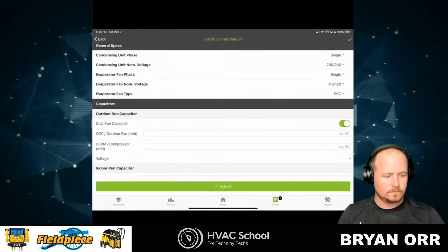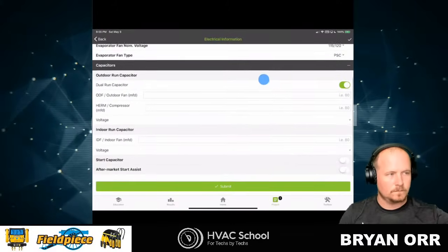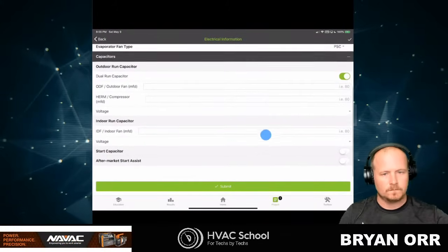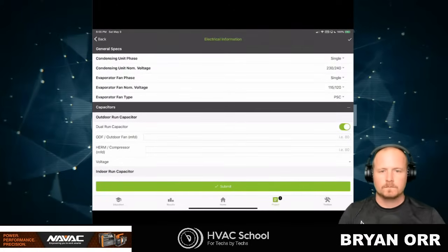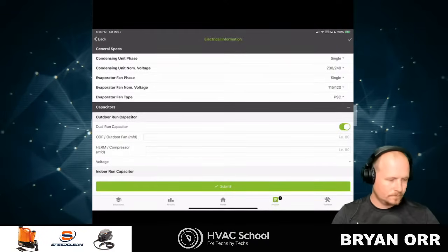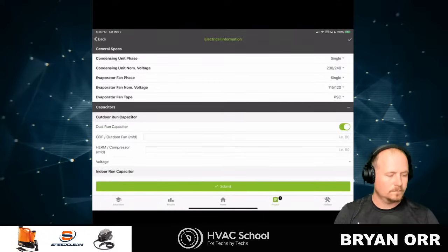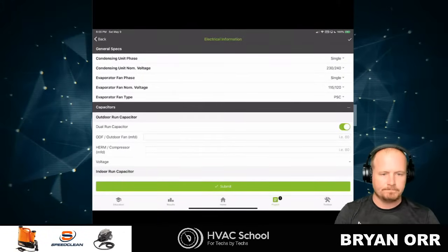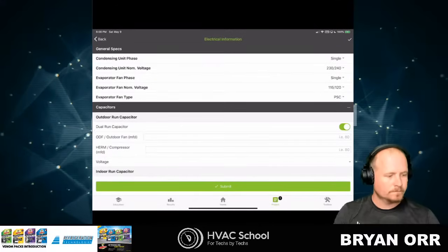And then on voltage, not yet, but in the future it will look at utilization voltage and tell you if you're in the correct range for the utilization voltage and some things like that. And then it also uses it for power factor, so for an assumed power factor, if you don't have a meter that measures power factor. So a lot of little things in there that voltage plays into.